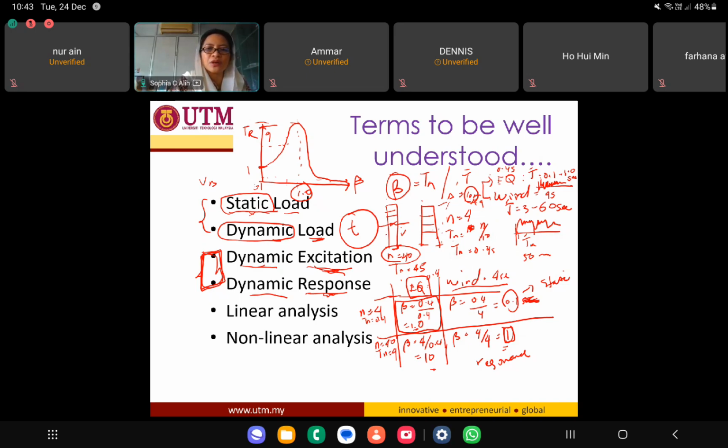You are looking at your earthquake load as a static load. It is acceptable for cases where the earthquake load is not governing. However, when you are designing a structure in which earthquake load can govern your building, it is also advisable for you to look into the dynamic analysis of that earthquake load impact to your structure.